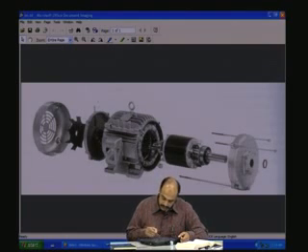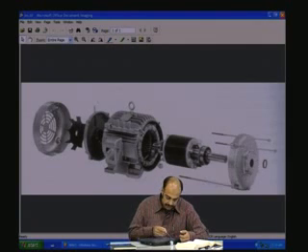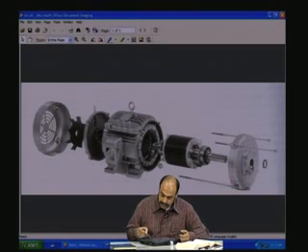And this rotor is inserted into it, and then you have the end facing plates. These are the end plates here. This is one end plate and this is one end plate that is fitted in through these bolts. And then there is the bearing, which you see also here, which fits into this, and that will cause a smooth rotation of the shaft here.